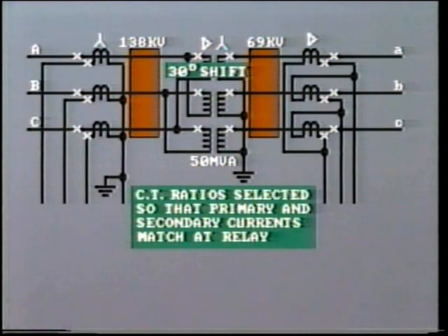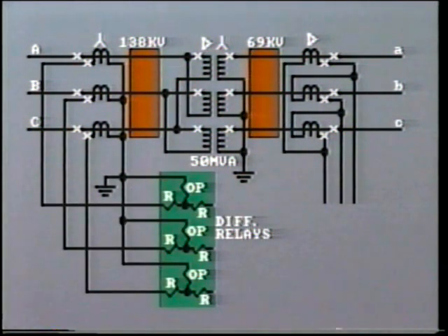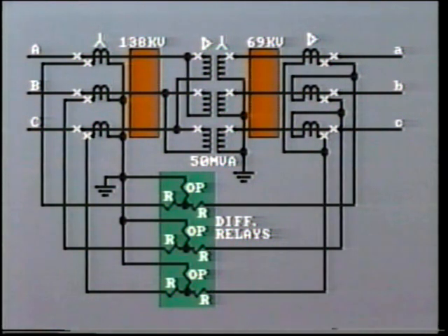Of course, the CT ratios must be selected to allow for the different secondary currents resulting from Y or delta connection. It's easier to connect the Y-connected CTs to the relay first. Then make connections from the delta-connected CTs to each phase relay so that both sides correspond to the same primary line. Let's check this. First note, we have indicated the currents inside the delta-connected primary windings to be IA, IB, and IC.